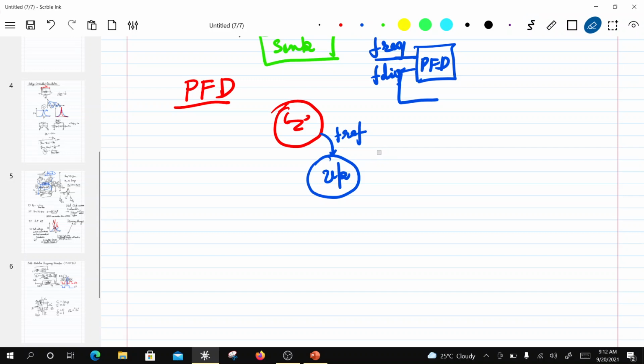So this is the up state. Now if FREF continues to come higher, then it is going to remain in this state. Now if FDIV comes first, then I will go out of this up phase. So if this FDIV comes in, I'll go out of this state into a high impedance state, right? So this is how one of the states is working.